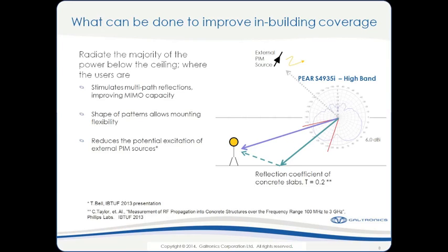that's a tremendous feat. Now, if 6 months or a year from now you decide that just that 3G installation isn't really what I want in that environment, I want to upgrade or add LTE to that small cell, I don't want to have to go back and resubmit for all my permitting and licenses again. I would like to simply do a maintenance call where I replace the box on the pole and not the antennas, and be able to add that capability. For some reason, municipalities and zoning laws are concerned about antennas more than they are just the electronic boxes. So you don't want to be having to go back and replacing the antennas later. So what that means is, install multi-band broadband antennas from the get-go, from day one, so that you don't have to reapply for permitting and licenses down the road.